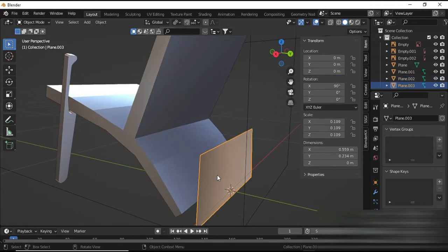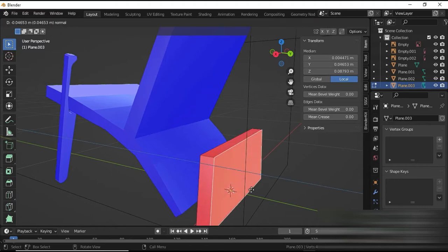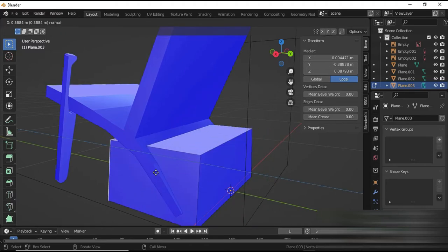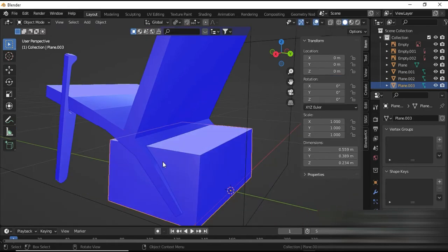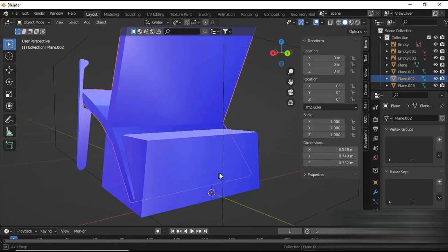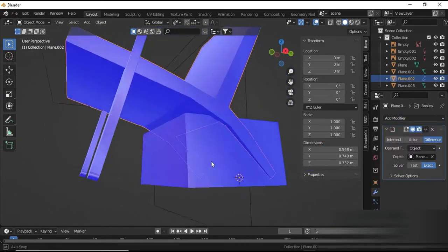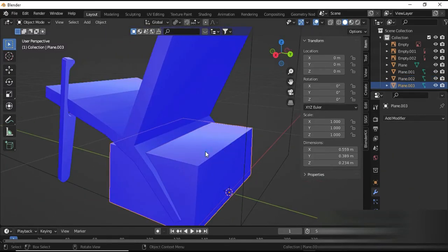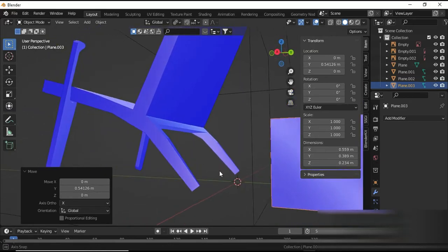I'm going to show you in a little while. So the scale is good. From this point on, I have kind of fast forwarded the video a little bit, and this is the second check. Make sure that the normals are in the correct direction. This is very important. Otherwise, you're going to have a lot of problems in your models. So, of course, we cannot extrude it on the opposite side, which is that red color. We have to extrude it on the left side. And as you guys can see, our boolean is successful.